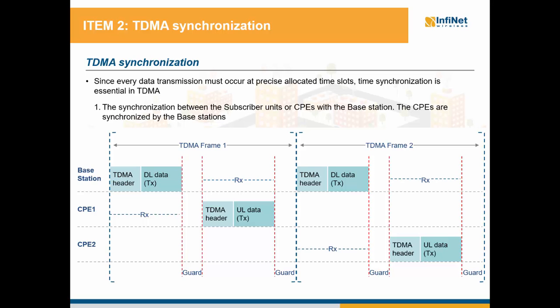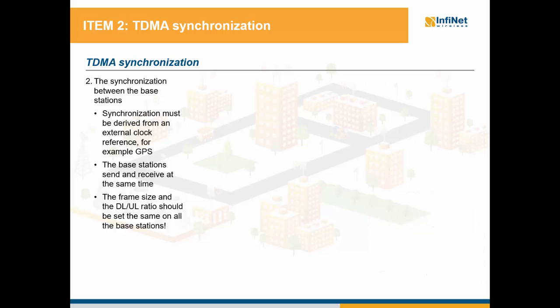However, if you have collocated base stations, this introduces a new synchronization aspect. When we collocate more base stations into one fixed location, and of course in case we don't have a distance separation between the base stations, then it's mandatory to connect these base stations to our GPS synchronization module in order to synchronize them and to set the same timing reference for all the base stations.